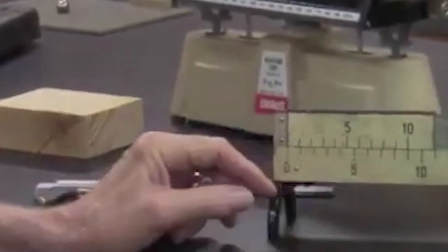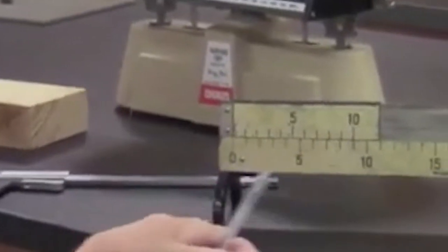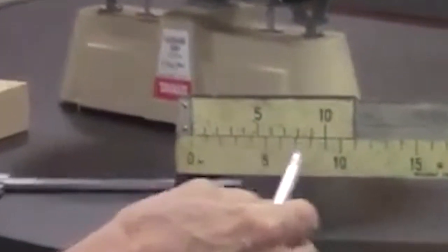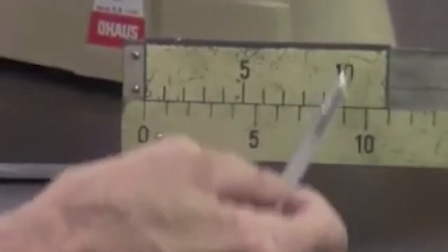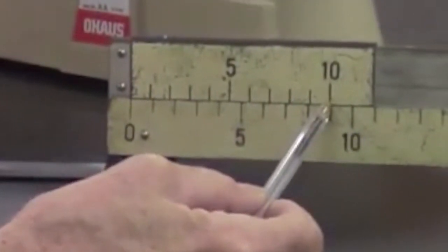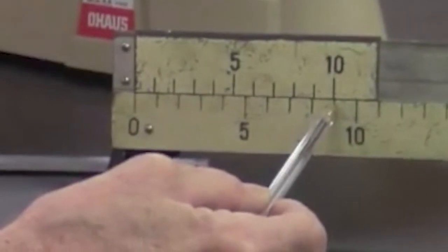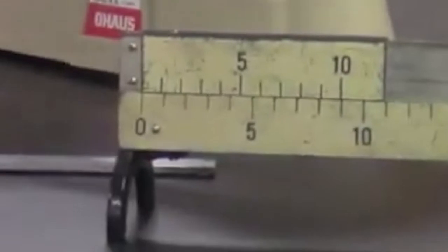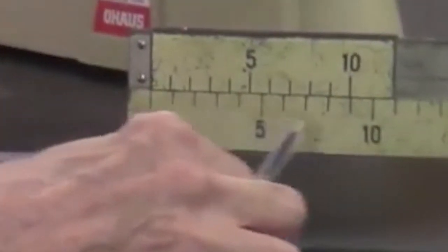You'll notice that the scale here has 10 divisions, and the scale down here, which is the actual millimeter scale, this is a simulation of the millimeter scale, also has 10 divisions. But this 10 here is kind of hovering over the 9 mark. What that means is these spacings here are basically 9/10 of the spacings over at the bottom here.